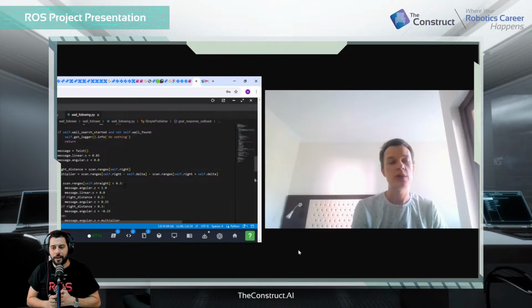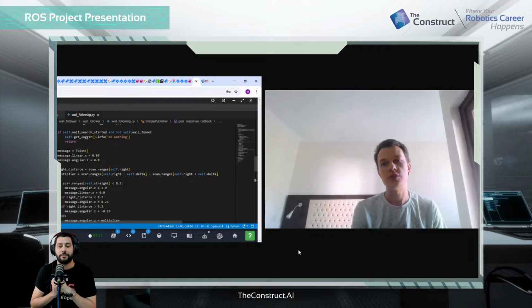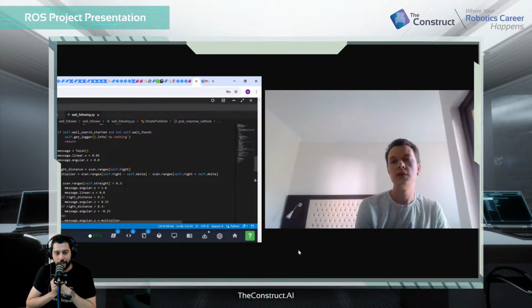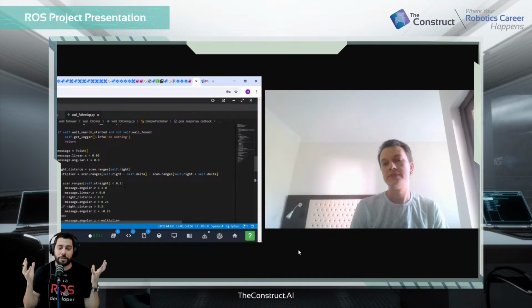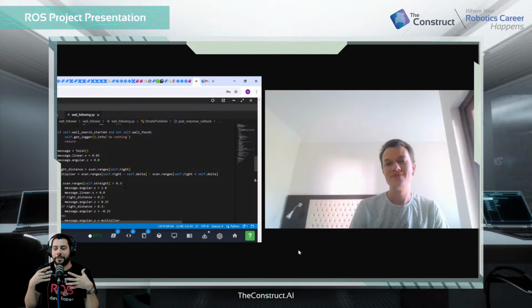Yeah, we can set, for example, some timeout, and if the timeout is reached, we abort the action and return a false result. Or make the radius bigger, which is what we did. Sure. Afterwards, when the process is done, stop the robot and kill the node, so that way we don't have to scroll up and try to find the result of the odometry points.